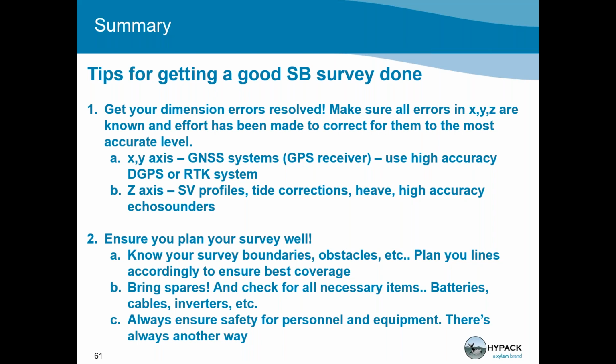An example of this is in the X and Y axis. You have to check what kind of GNSS system you're using, whether GPS, GLONASS or BeiDou, and make sure that it's on a high differential setting, or that you're using an RTK system if possible. In some cases, if you do not have both, then you can use land-based corrections or satellite-based corrections.